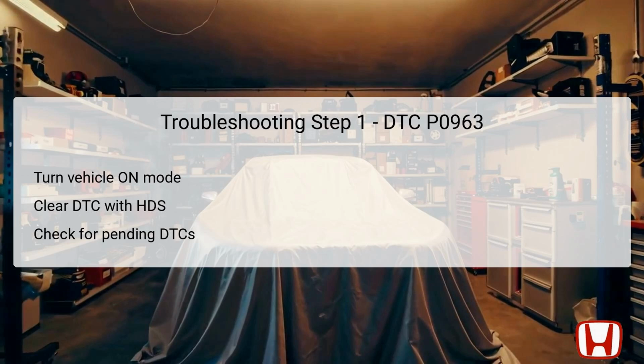Following that, restart the engine and wait for approximately 1 second. Check the HDS again for any pending or confirmed DTCs. If P0963 reappears, that indicates a confirmed failure, and the next troubleshooting steps must be pursued. However, if it does not reappear, it may suggest a temporary issue. In this case, inspect for poor connections or loose terminals.